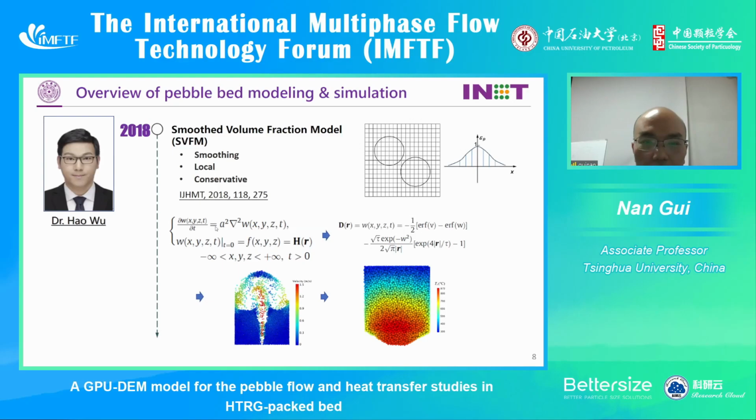We use the thermal diffusion equation. We can regard the W as the particle's mass, and let it diffuse to a local region. And we use an analytical expression to calculate the mass of the particle in each cell. Then we can calculate the volume fraction in each cell, and this distribution of volume fraction would be very smooth, which is a benefit for numerical simulation stability.